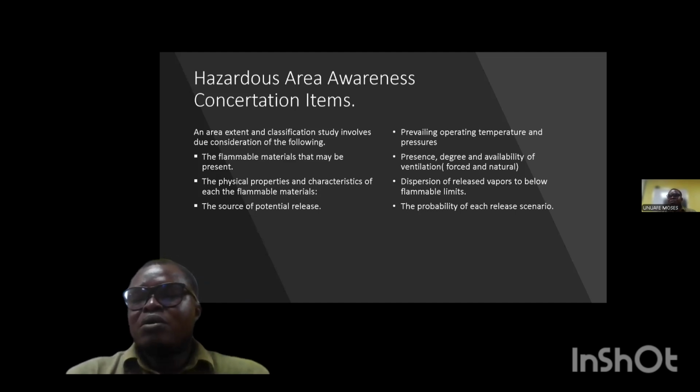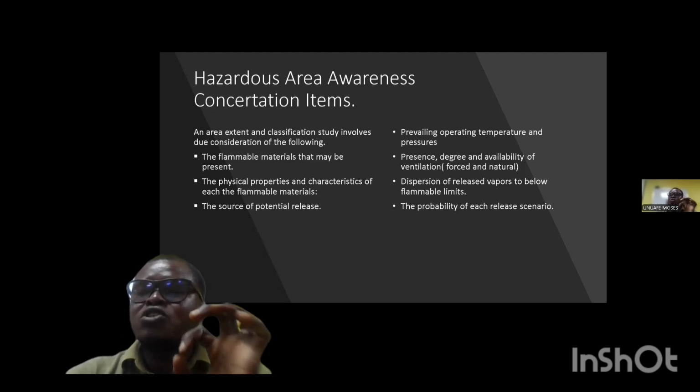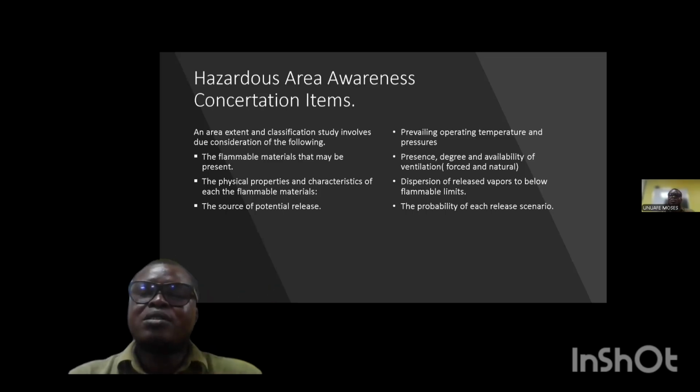Let's take a similar example that normally occurs in a depot: a sampling point on either a chemical line or a product line, where an operator collects a product sample. Even if it's tightly sealed, each time it opens, there is a chance of vapor escape, making it a source of potential release. That is a clear example.